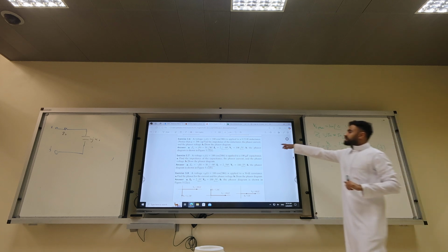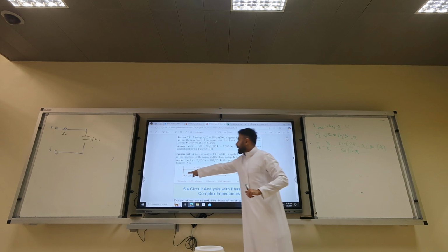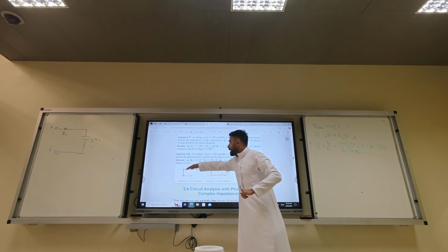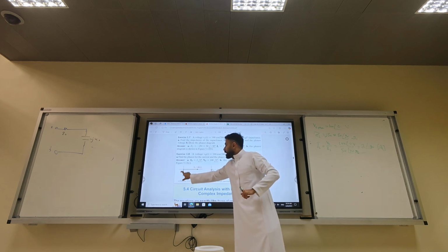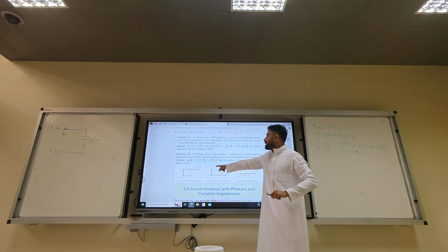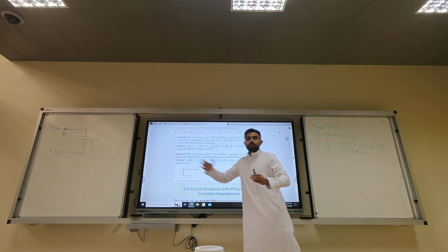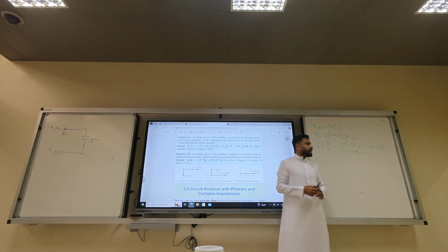Now he's asking you how to plot it. So 100 angle 0. The current is 2 angle minus 90. So who's leading? Voltage leads the current. Look at the acute angle, then you decide.